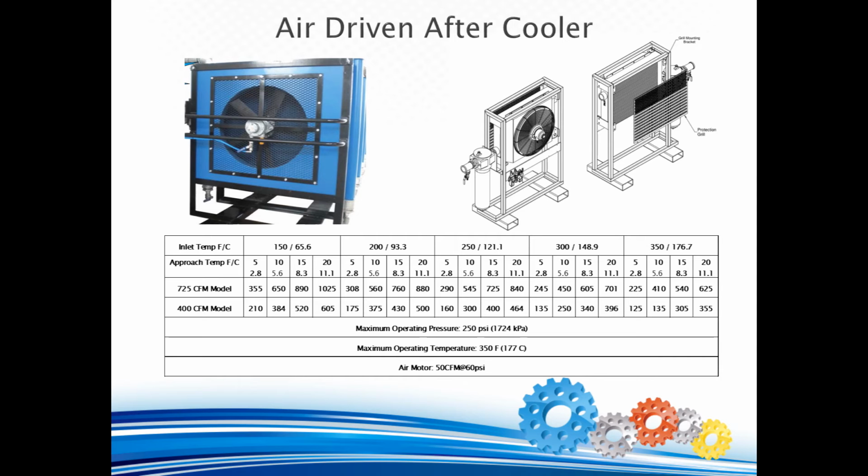Because the approach temperature can never be zero, it can also be surmised the target air cooler output temperature can never equal the ambient temperature. Hence, an aftercooler can never remove moisture 100%, and the compressed air output from the aftercooler at temperatures below the air cooler output temperature will be fully saturated.